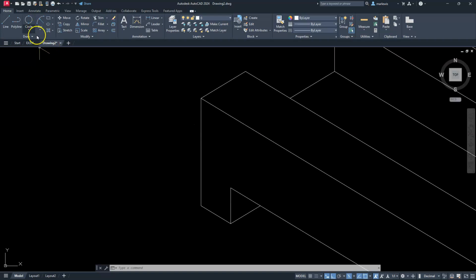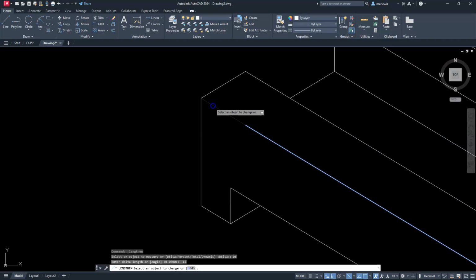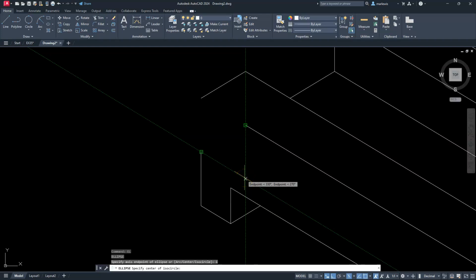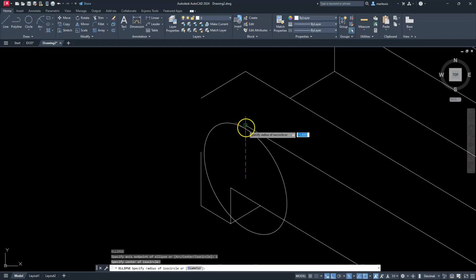All right, so what I need to do is go to lengthen. I'll choose the delta option, tell it -15. Select this line here and this line here. Escape. I'll type in EL, that's short for ellipse, enter. Then I want to type in I for ISO circle. What I'm going to do is touch this endpoint, and then touch that endpoint. I'll come straight down to where they meet, which should be somewhere here. Left click here, and then go up to that endpoint.